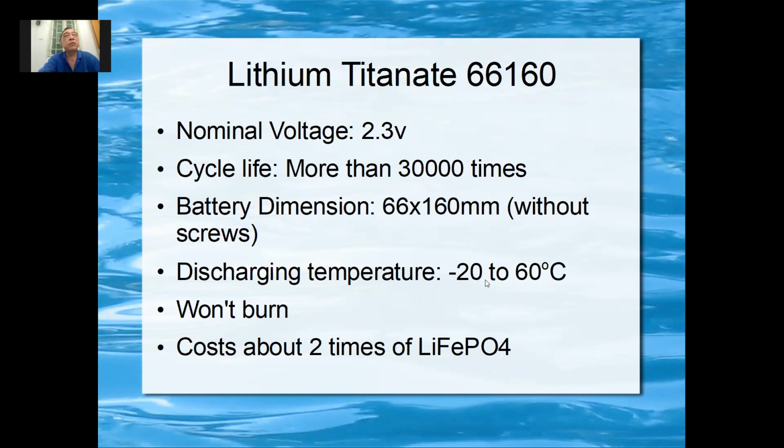So that will be useful for a car, let's say, parked under the snow. And then your battery cannot work. So a Tesla car, if it's in the snow, it will not work. That's why they have insulation and a heater. When there's snow and the temperature drops too low, the battery will run the heater to heat up the battery, to keep the battery above freezing point. So you actually consume energy just to keep warm. Just like yourself, you've got to burn energy to keep yourself warm.